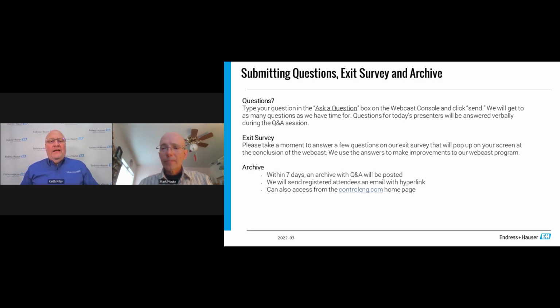Again, I caution everybody, verification is just that. It is a qualitative assessment. It is not necessarily covering everything that you would cover in a complete calibration. So there is a difference. You're certainly not going to see any deviation information, things of that nature. So while we certainly encourage everybody to take full advantage of things like verification, we're not advocating that you don't calibrate anymore at all either. I think it's a very conditional, case-by-case situation on what makes sense for that particular process or that particular measurement.